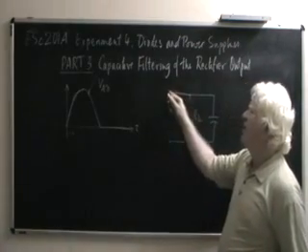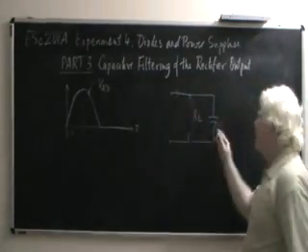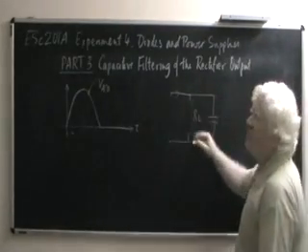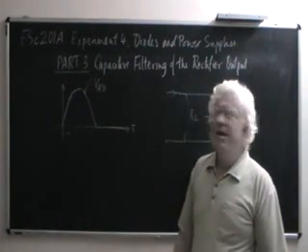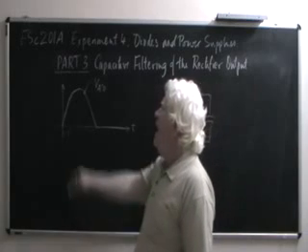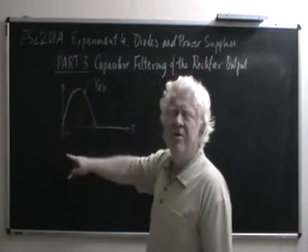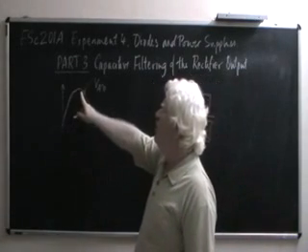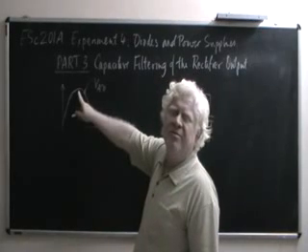So the diode in the rectifier behind this is also ideal. So this capacitor has been charged to what we can call Vm, the peak voltage of the sinusoid. In the first quarter cycle, as the rectifier output voltage rises, the capacitor voltage will rise side by side with it. It will reach its peak value at this point, and after that something interesting happens.